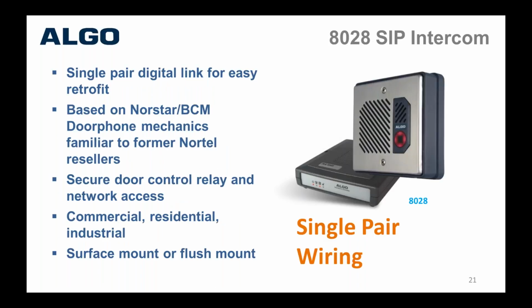This device is our most popular product at the moment. It's a 2-part solution, so you have that same intercom, but the advantage of this product, due to the 2 parts, is you don't require Cat5, Cat6 cabling where the intercom is. It will run on single twisted pair, 300, I think, to 400 meters. I think we specify 330 meters.